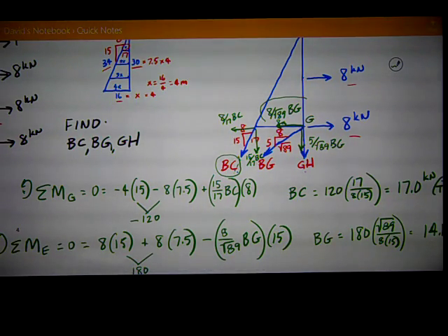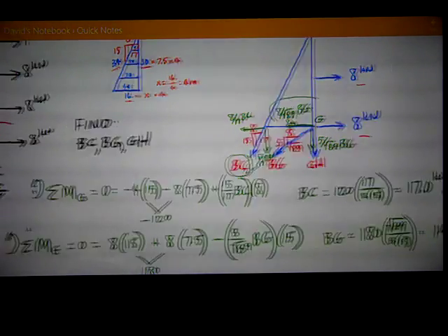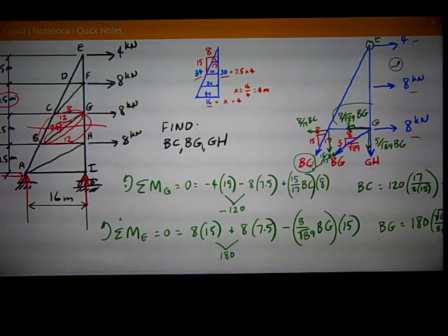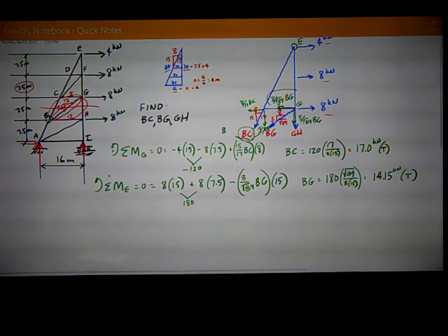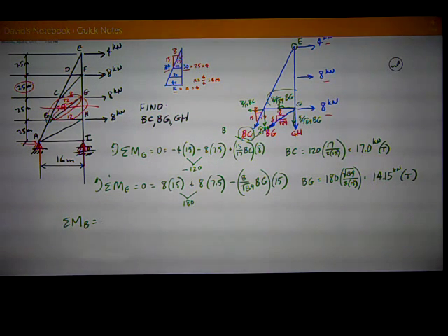Connect those 2 points, BC and BG, where they intersect. They intersect, looking at my truss, at point B. So I want to sum moments about point B, which, like I say, is actually off the truss, but it doesn't make any difference. It's still a point in space that I can sum moments about, and it eliminates a lot of unknowns. So I have sum of moments about point B is equal to 0, and that's equal to, I have to consider all 3 of those external forces.